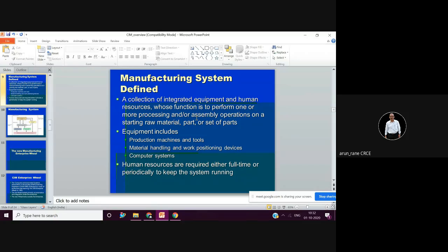Then in the case of furniture lines or cupboard manufacturing lines, like Godrej, the raw material in the form of sheet metal enters, and then different operations like punching, pressing, joining, spot welding, then painting, then assembly of the cupboards, everything is done on the line. And then at the end you get a finished cupboard. So there is no inventory. Work in process inventory is zero.